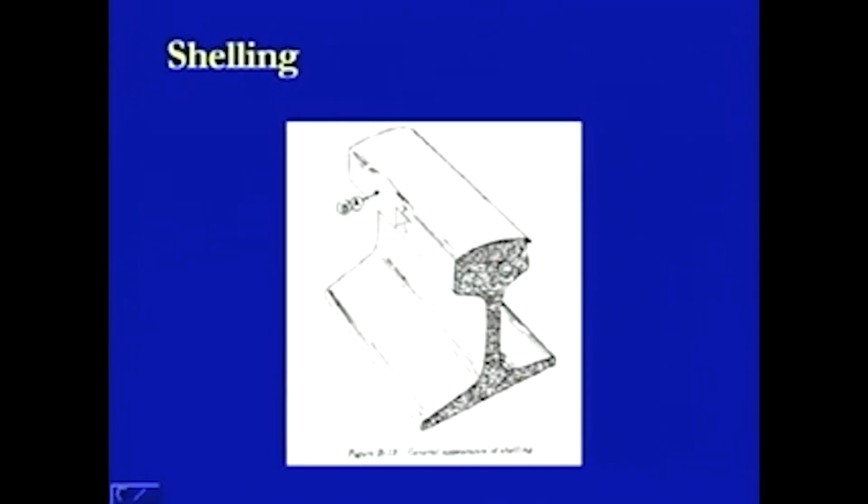One way of dealing with these types of conditions is that we just change the face of the rail section. So, if in the initial condition this is the inner side of the rail section, then we can make this the outer side of the rail section, and just turn this rail like this, so the outer side becomes the inner side. In that case, we can use the same rail for some more time, increasing the life of that rail section. So, in all these cases, we have seen that there are different types of defects which can take place in any rail section.